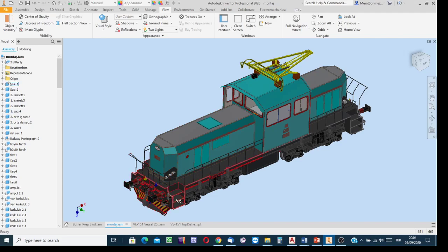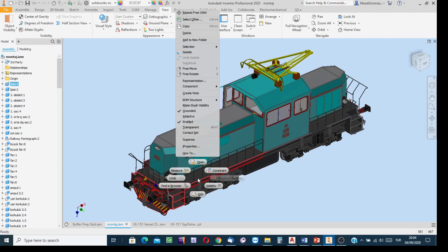It is the main chassis. Indicated with the left click, right click the mouse. Then in the menu that will appear after right clicking, do not select edit, do not select open, respectively. The edit button is to have the selected component as active, but the rest as inactive. But if you select the open option and click, then the selected one will be in a different file. If it is a sub-assembly, an assembly file. If it is a component, a part file.